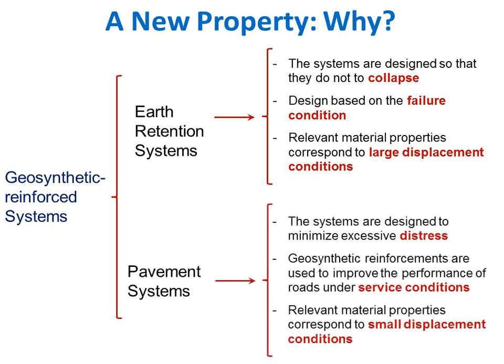And it breaks my heart when I see specifications specifying reinforcements for bases that specify a tensile strength. By the time that those reinforcements reach their tensile strength, the pavement is long gone. But to be very honest, that's what we have inherited from learning how to use reinforcement. So those are the type of mechanical properties that we have been using.